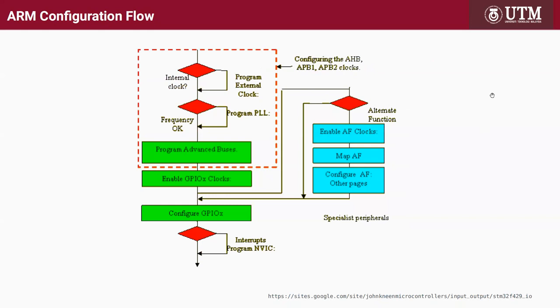Okay, here is the plan. If you want to use the I/O port on ARM on STM32, you cannot just go ahead and do it like in AVR or PIC. Most microcontrollers, I think, default the ports to output.